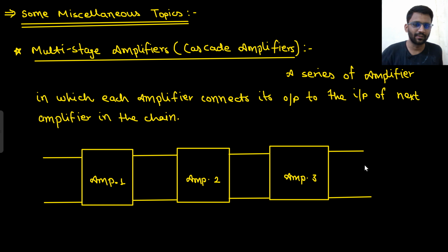This is stage 2. Right. So what will be the gain here? Let's assume this potential is Vx. First tell me, what is my Vx by Vs? That is minus Gm into Rd1, then R1 parallel R2 divided by R1 parallel R2 plus Rs.